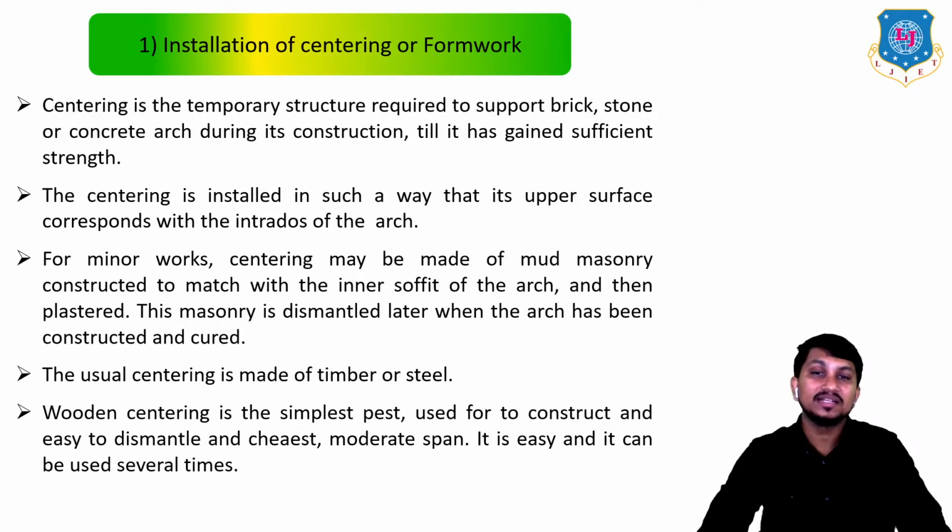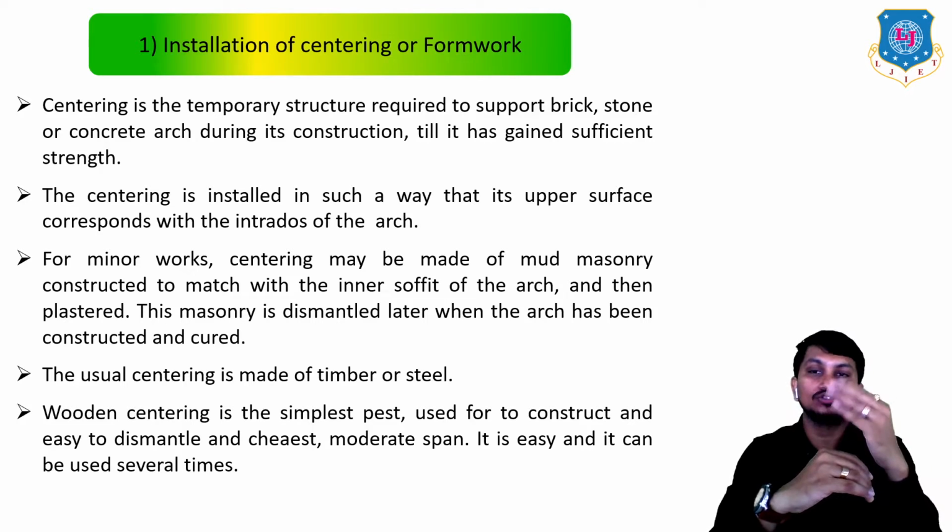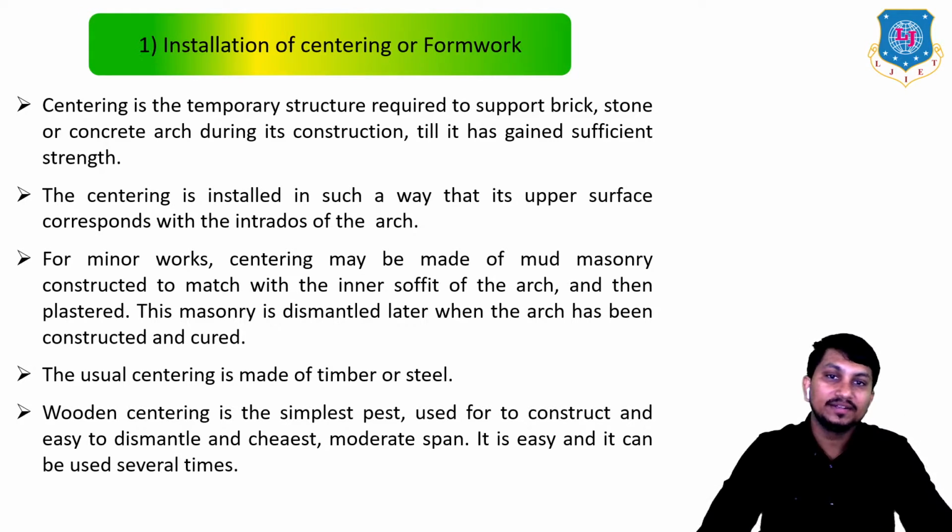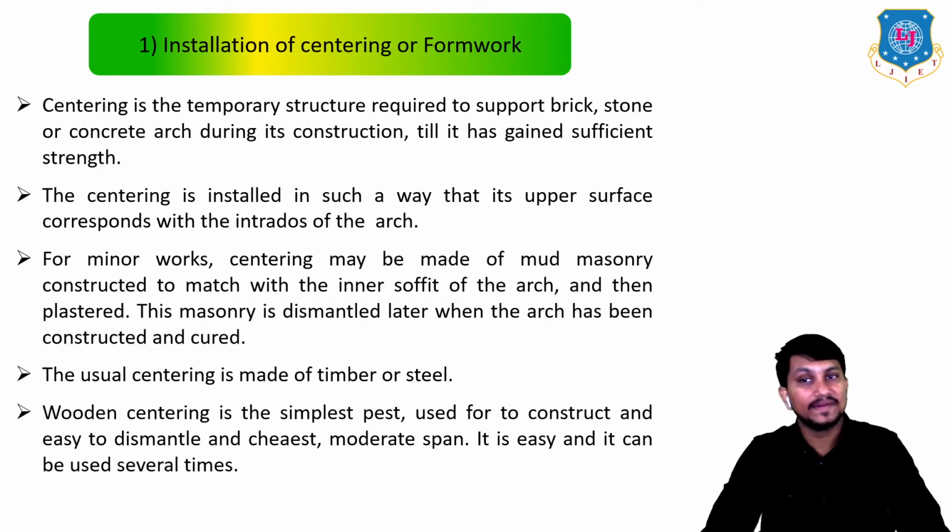This centering is a temporary structure required to support the brick, stone, or concrete arch during its construction till it has gained sufficient strength. The centering is installed in such a way that its upper surface corresponds with the intrados of an arch. For minor works, centering may be made of mud masonry constructed to match with the inner soffit of an arch and then plastered. This masonry is dismantled later when the arch has been constructed and cured.